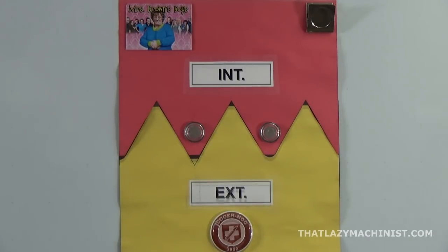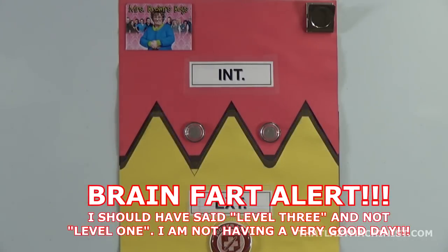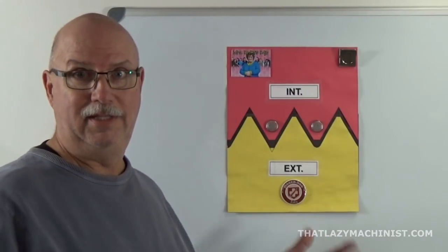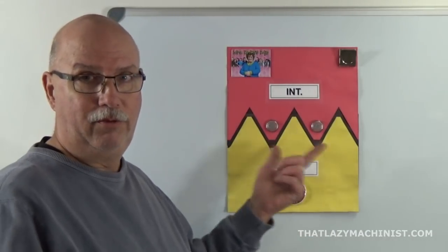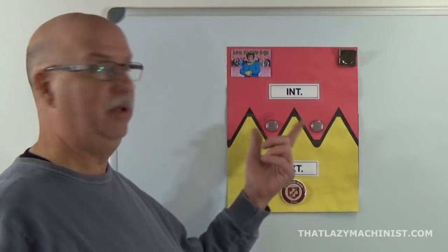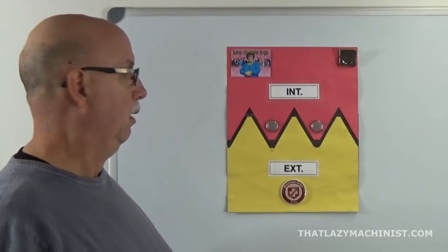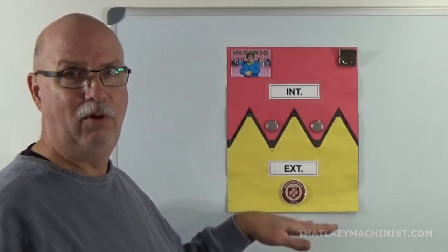So if we look now at a class 2, we see that we get a little more play here. And finally a class 1, where we have a lot more play. Now you may have noticed as we cycled through the different assembly classifications from a level 3 to a level 1, 3 being the tightest and 1 being the loosest, well, that the bottom or the external thread here is the one that moved.